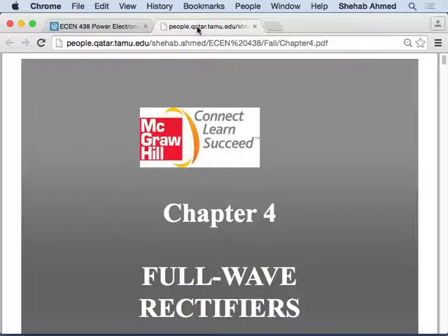So you're able to calculate the capacitor in cases where you have a capacitor rectifier, you're able to use the equations for the current waveform, calculate beta. You're able to do this kind of stuff. If you're able to do that, the full wave rectifier's solutions will be almost identical. The only thing that will be different will be the waveforms and maybe a few terms in the equations. So it's not much different. That's the full wave rectifier.